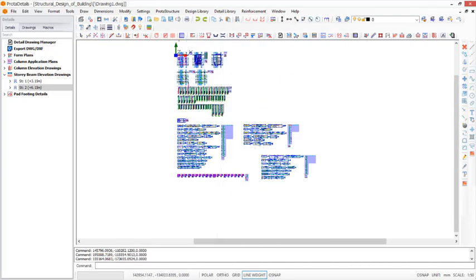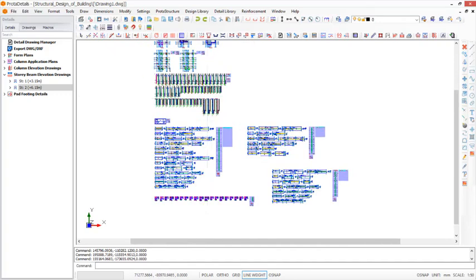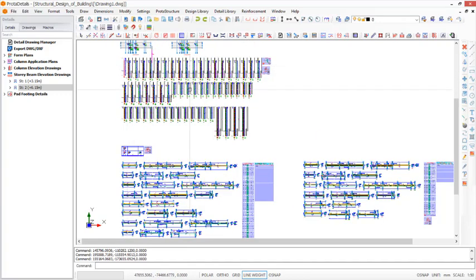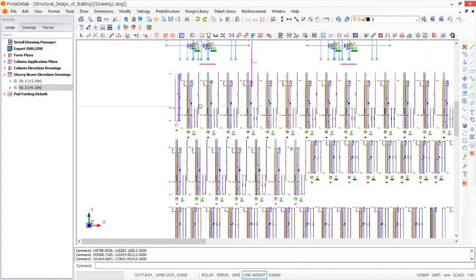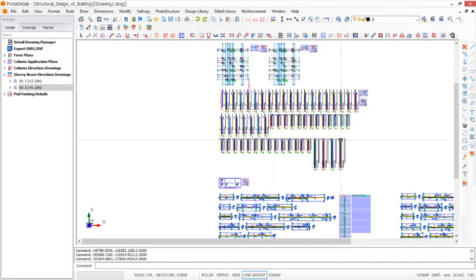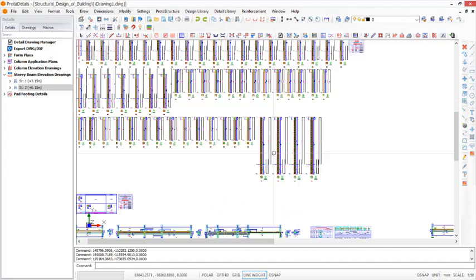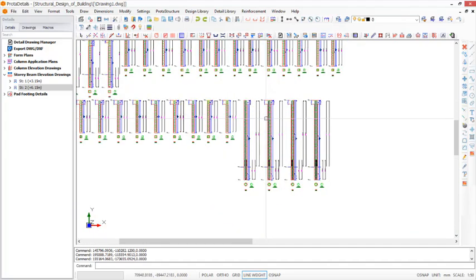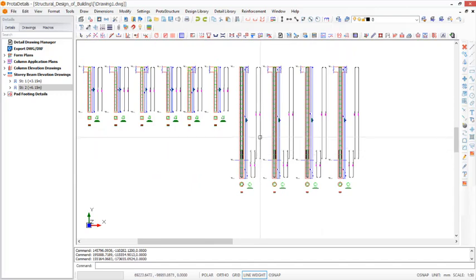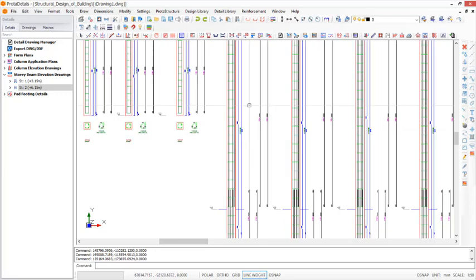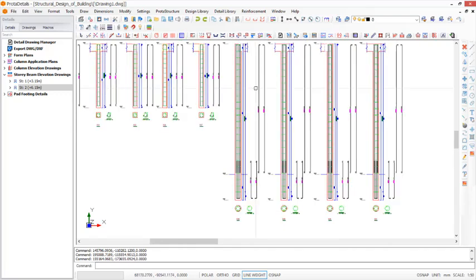So after which, what we have to do now is we need to redraw the columns. As you can see, these columns have been drawn story by story, okay. It is fine, you always draw your columns as it connects from the foundations through the first floor to the roof. Basically, if you are designing a high-rise structure, it is fine, your columns' details cut through all the stories to the roof level, so you can ease your editing experience.